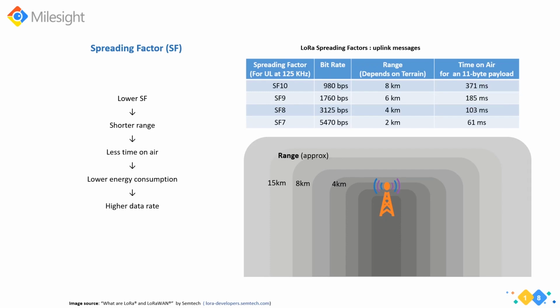Okay, here you can see in this picture, the color orange stands for the gateway station, the LoRa 1 station here. As the distance increases, the signal is sent with the spreading factor stepping from 7 nearby to 12 at a distance. So you can find a relationship between the spreading factor and the range. The higher the spreading factor, the bigger the range you can reach.